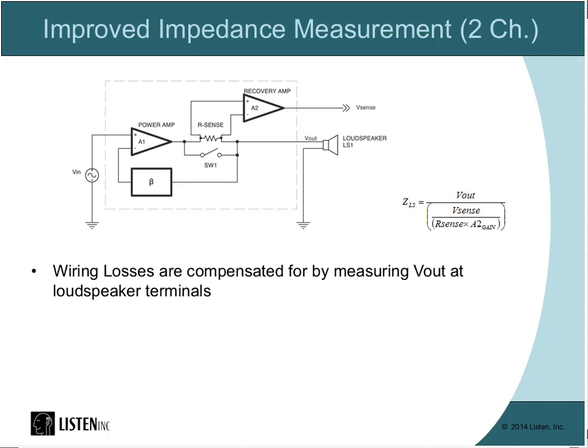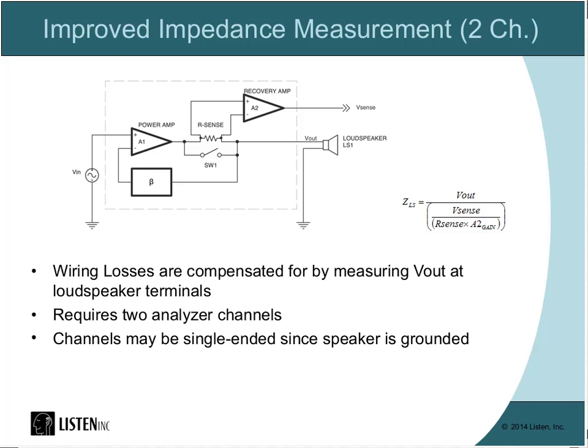And again, preferably you want to measure right at the terminals. We now have two simultaneous measurements, the sense, V-sense, as well as the voltage across the loudspeaker. And channels can be single-ended since the speaker is grounded.